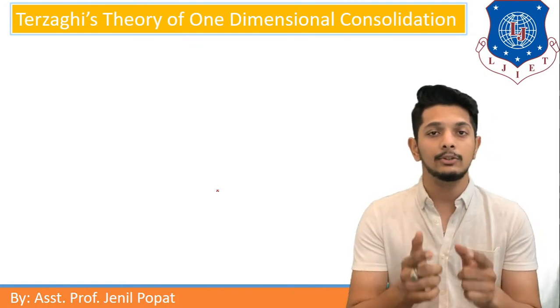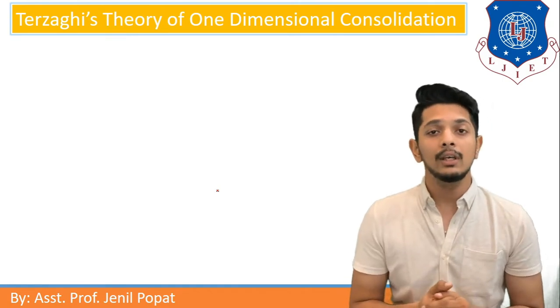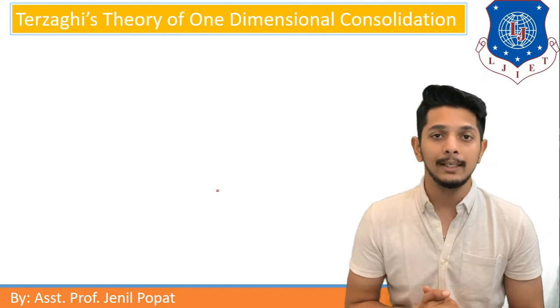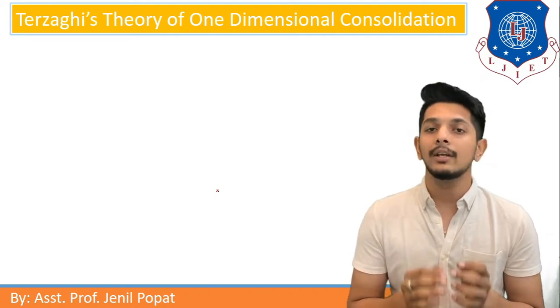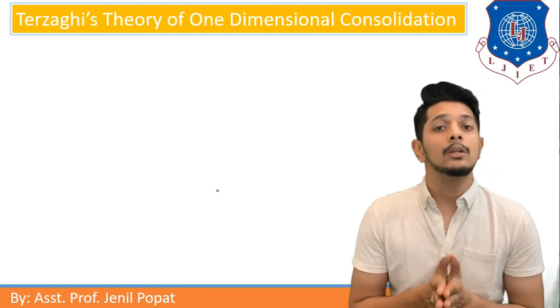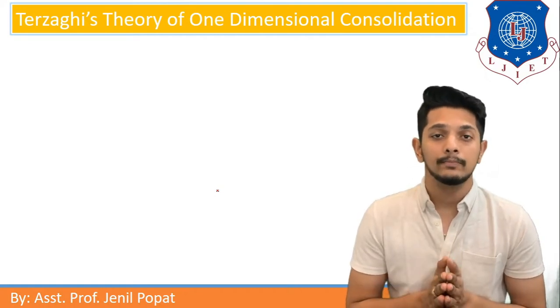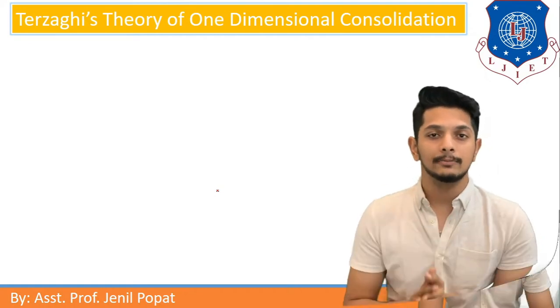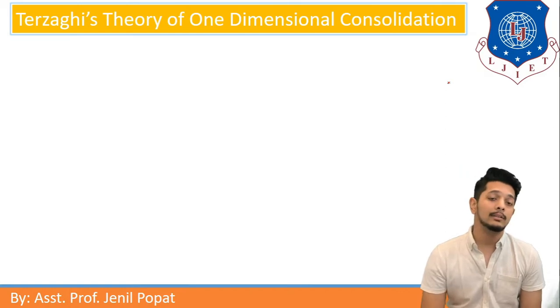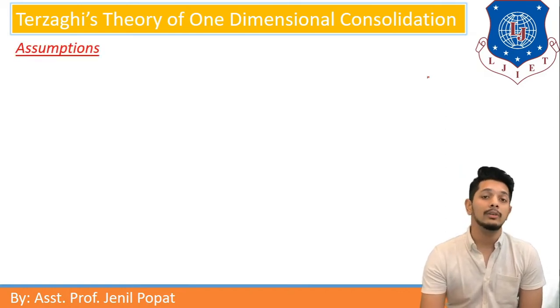This is video part 2. In this video, we are going to learn Terzaghi's one-dimensional consolidation theory as well as consolidation test setups and square root of time fitting method. Let us start. Terzaghi's theory is among the most popular theories for consolidation. Let us understand the assumptions for Terzaghi's one-dimensional consolidation theory.